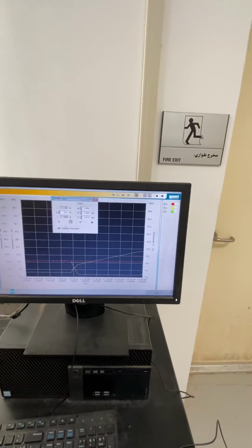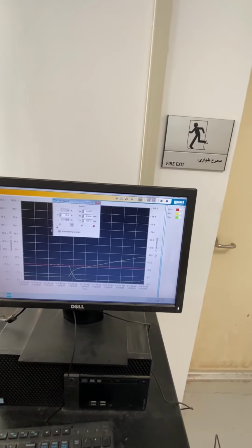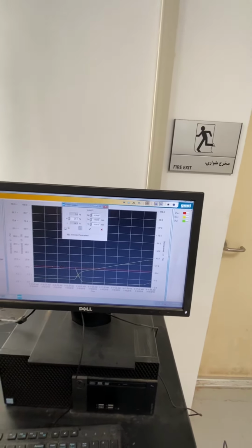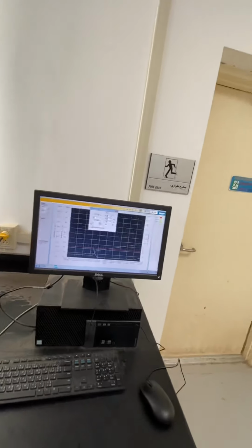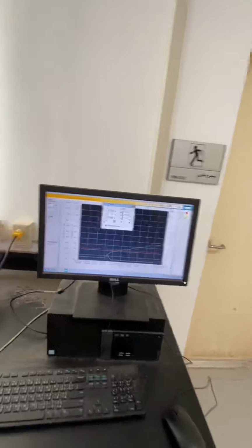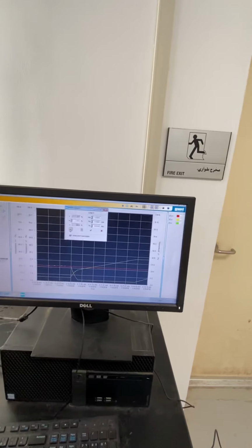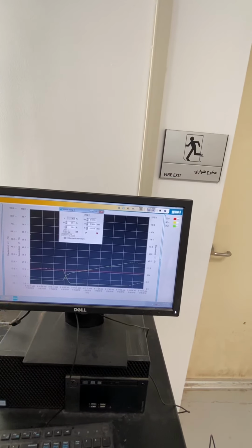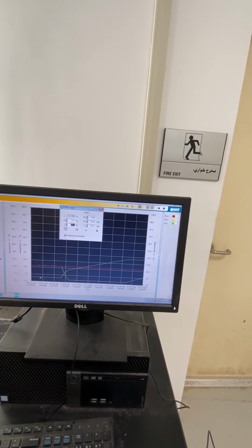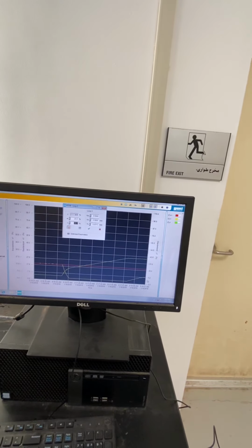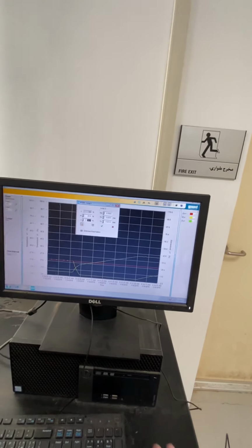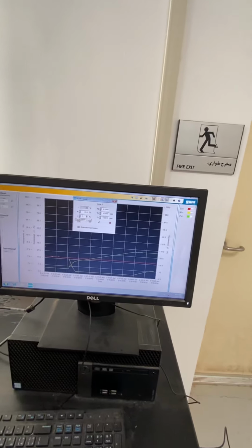In this situation, it is highly recommended that in order to bring the system back to the normal situation or the previous situation, you switch back to the manual mode and then have a look at the output signal. It is almost 6%. It was 39.